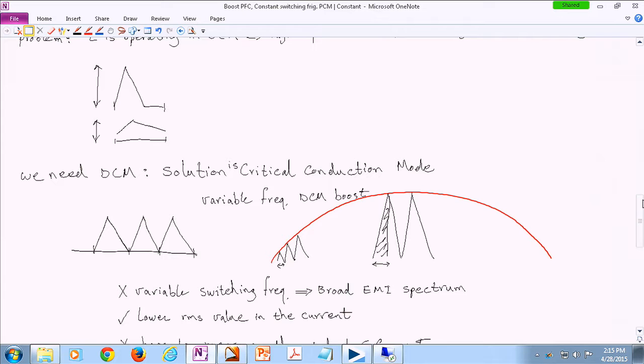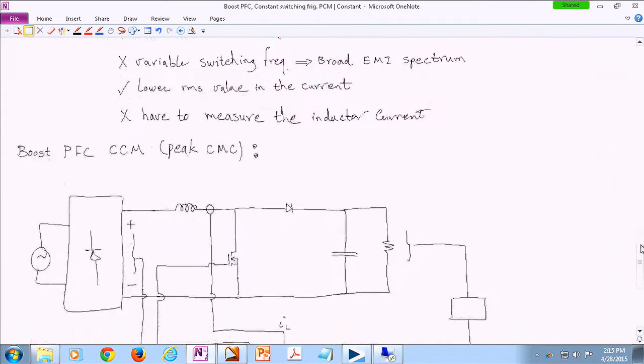As soon as the current gets back to 0 or tends to get really close to 0, you start the next cycle and just keep repeating that. I didn't have a simulation model for this, but as it turns out, it's almost the same thing. You can improve your power factor. You can achieve like 70 or 80% of power factor.